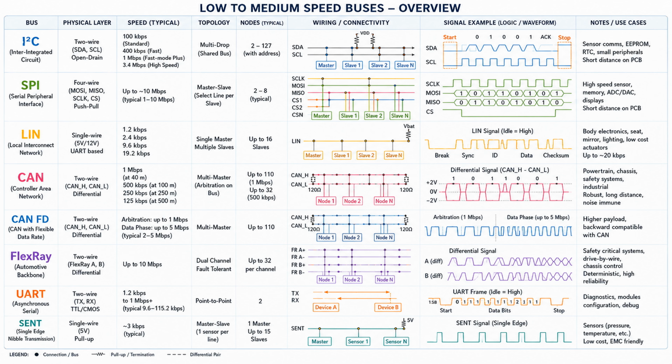Section 5 describes CAN-FD, CAN with Flexible Data rate. CAN-FD extends classical CAN. The arbitration phase still runs at standard CAN speed, but the data phase can run significantly faster. Typical data phase speeds are 2 to 5 Mbps, sometimes higher. CAN-FD supports larger payload sizes, higher throughput, and backward compatibility with CAN. This makes it highly suitable for modern vehicles with increasing sensor and ECU data demands.